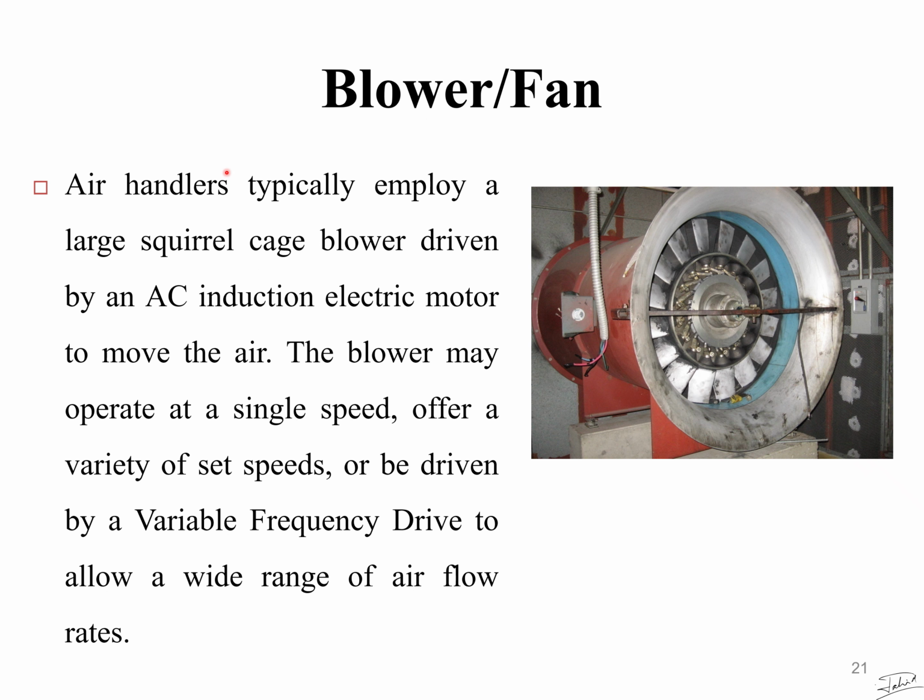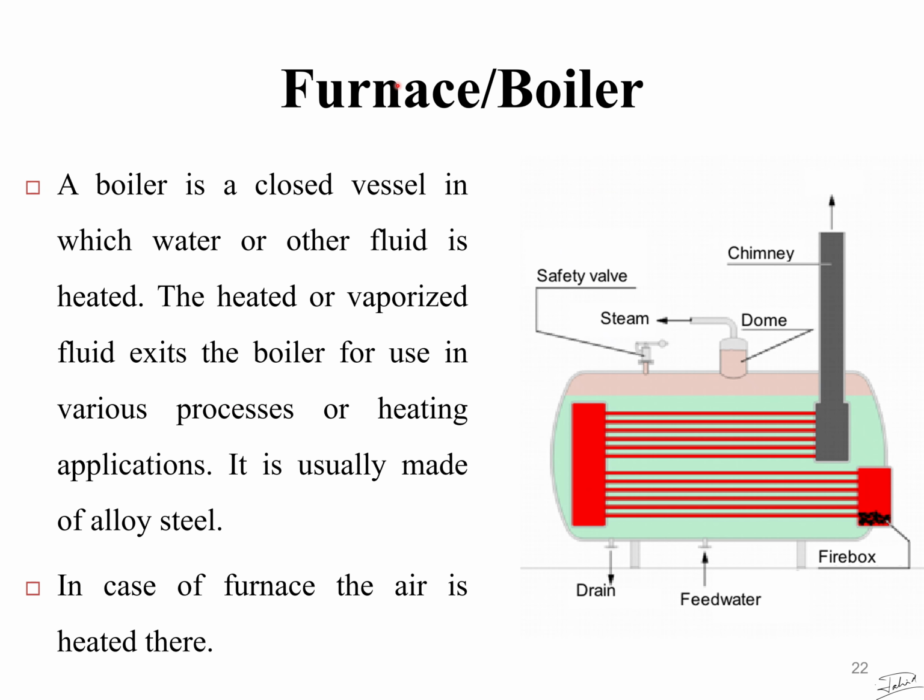Blower or fan. Air handlers typically employ a large squirrel cage blower driven by an AC induction electric motor to move the air. The blower may operate at a single speed, offer a variety of set speeds, or be driven by a variable frequency drive to allow a wide range of airflow rates. Furnace or boiler. That's why this system is called heating ventilation.